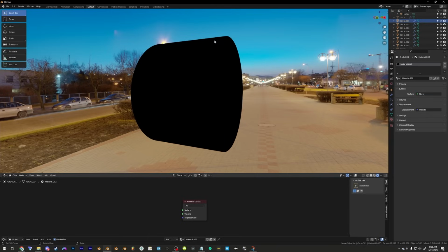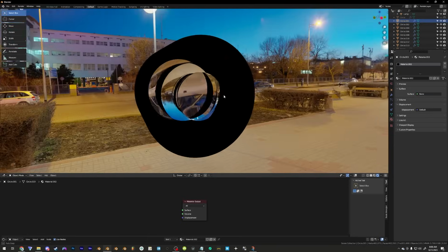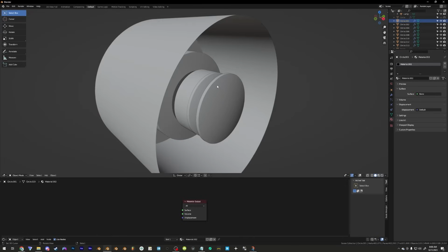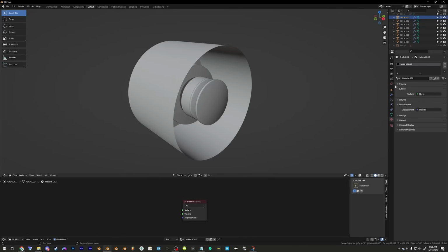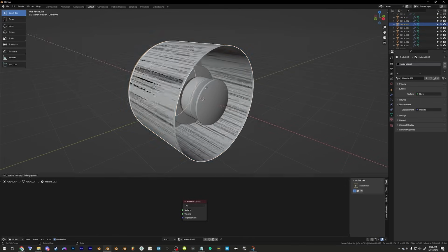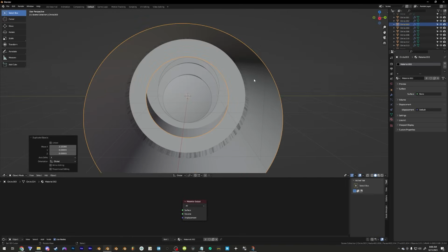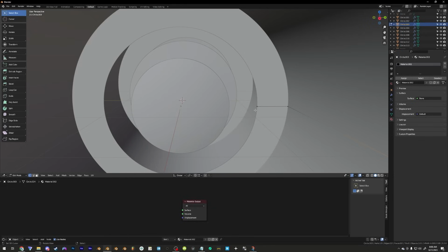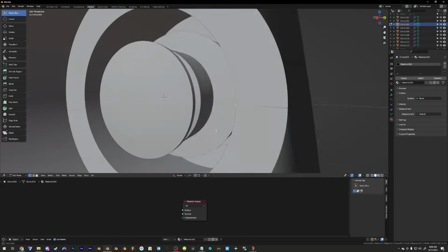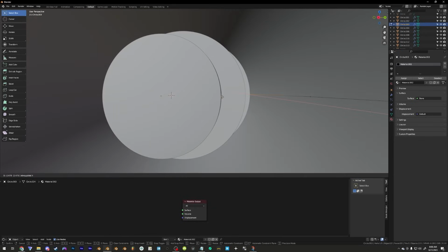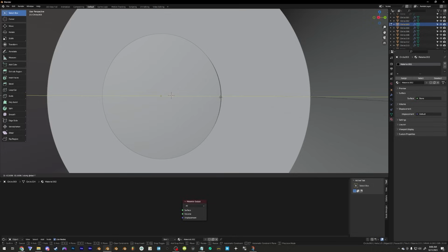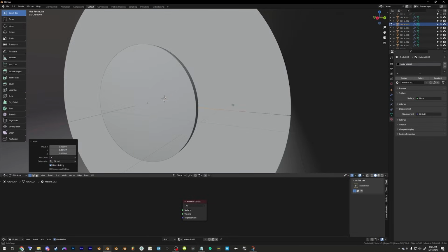Then we can just select our main circle right here again, and line it up with the back of our surface right here. So let's enable visible objects again, so we can scale it down, and then we can align this up with our vertice right here by just holding G, Y, and then holding Control, which is pretty convenient.